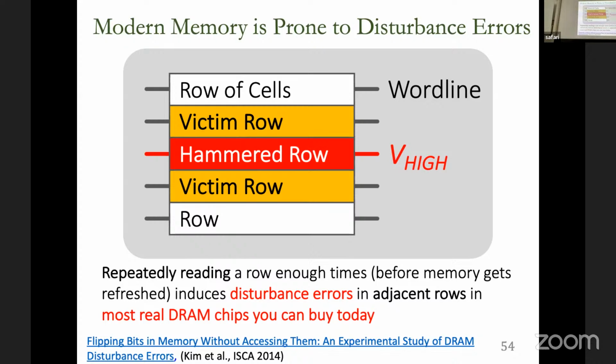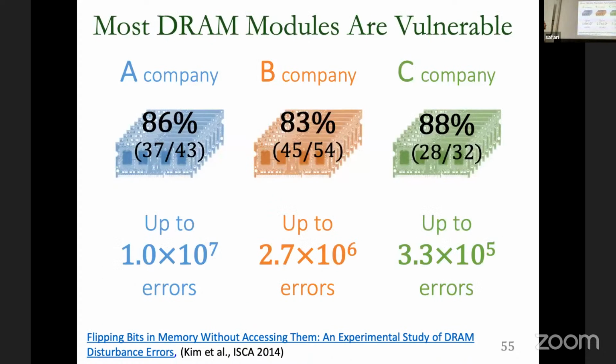So basically, the main thing that is actually enabling such bit flips to happen, this effect called read disturbance in current DRAM chips, is the fact that we are packing the cells for those different DRAM rows super close to each other inside the DRAM array itself. And many security papers have exploited this phenomenon to, for example, take over a computer or to reveal secret information from user space or user data.